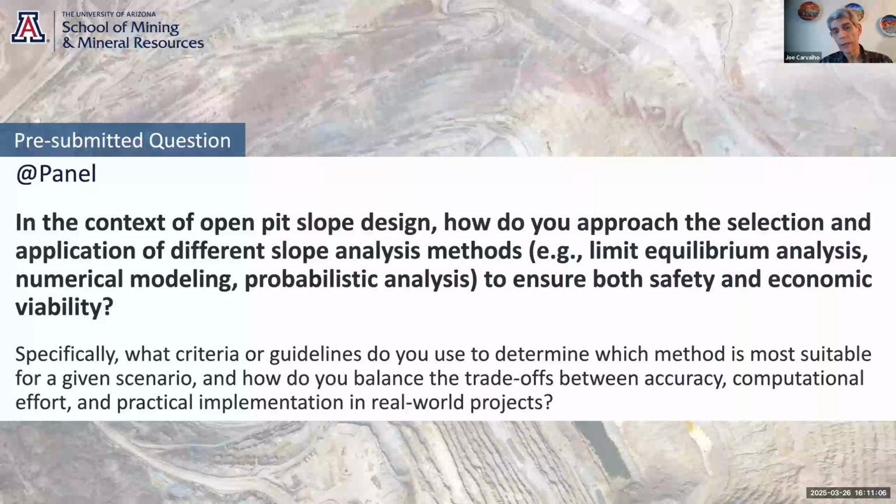And when you talk about probabilistic analysis, it's still quite a little bit prohibitive in numerical modeling, especially in 3D. It's totally available in limit equilibrium analysis. So it's interesting that even today, designs are based on limit equilibrium analysis, where numerical modeling is much more used for back analysis and confirmation of things. So yeah, there's no silver bullet here for a specific method.